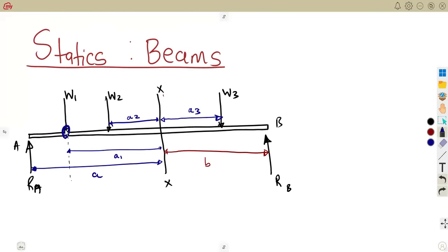If you are at this point, you are going to consider, what is it that you have on the left side, the force that you have? That is about the shearing force, guys. It's not something that is much. So let's just have it here. A shearing force, or when you are considering a shear force, it is the algebraic sum of all forces to the left or to the right side of the section. So I'm saying it is the algebraic sum.